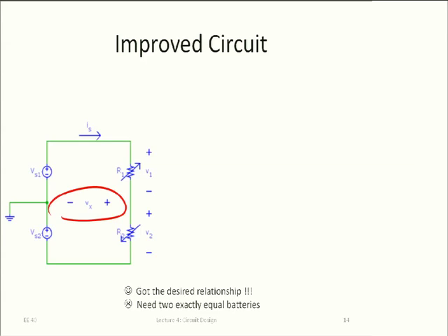We're going to run out of time otherwise, so I'll let you go through the derivation. I'll tell you conceptually how you do that. For example, you could write a KVL loop here, right? So then you have V2, VS2, which is given, of course, that's a source, and Vx, which is what we want to know. You have an equation among those, right? That's that KVL loop. And then, you can write a second equation for Is.